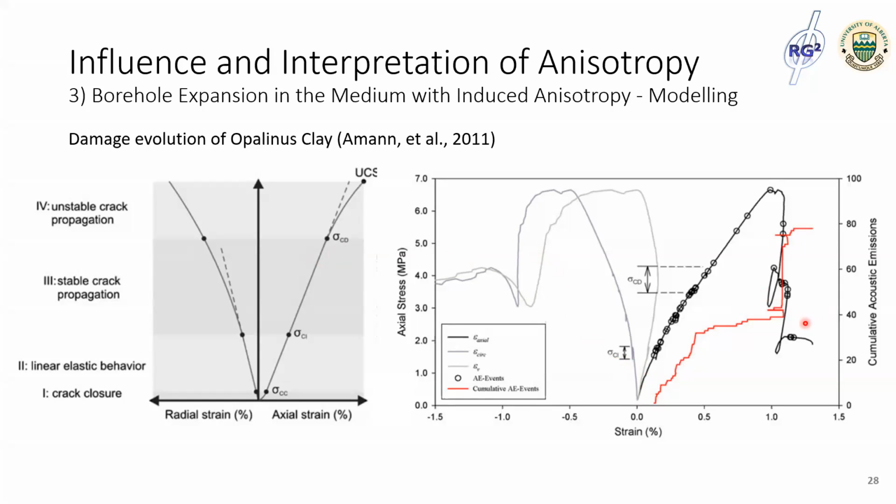The acoustic emission activities emerged at a very early stage of shearing, and therefore, the crack initiation might happen at a very low deviatoric stress. It also shows that the acoustic events stop accumulating immediately after the peak stress, which means that the damage might reach its limit.